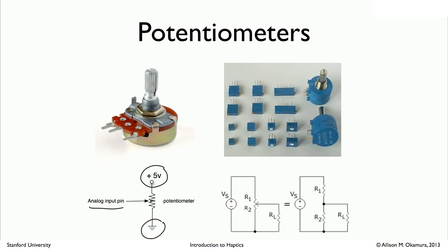And basically what's inside the potentiometer is a big resistor, and as you rotate, if you take your hand and rotate this knob here, it's going to move this pin which is touching the resistor inside, and it's going to change its position. And depending on where it's changing its position, you're going to get different amounts of resistance at the top of the circuit and the bottom of the circuit. And this can be shown by this diagram over here.